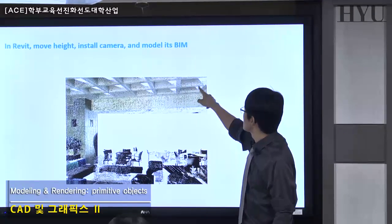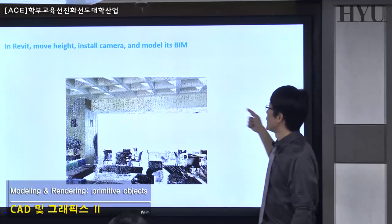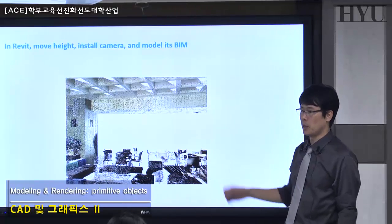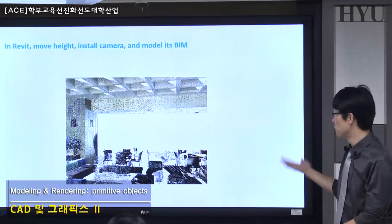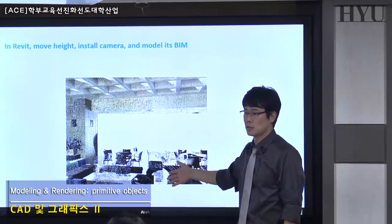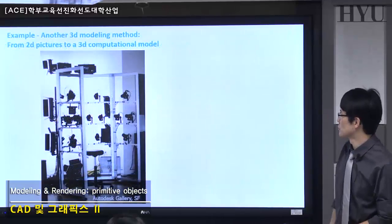But take a look at this white area. They are empty because at that time, the laser scanner was here. They are not visible from that laser scan. So we need to place it in two or even more places and then combine them so that we can generate almost perfect 3D geometry. And there are huge glasses. So external trees or buildings can be captured, but at that time we ignored them.